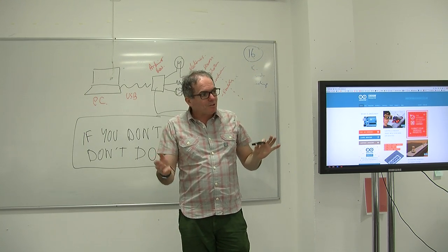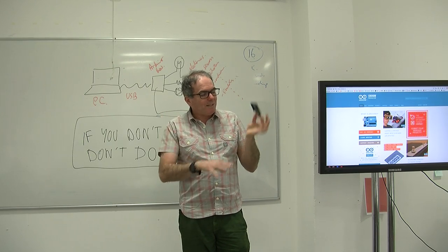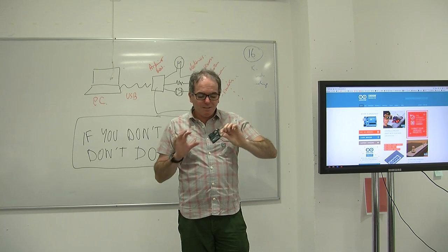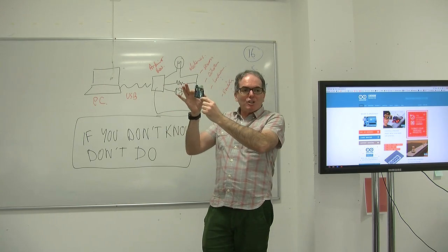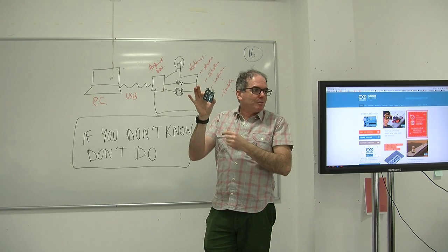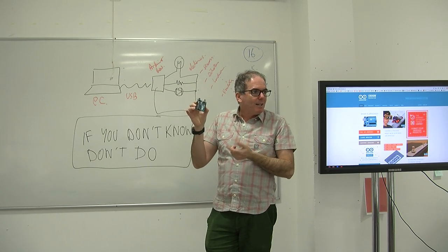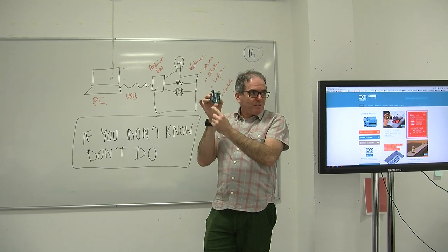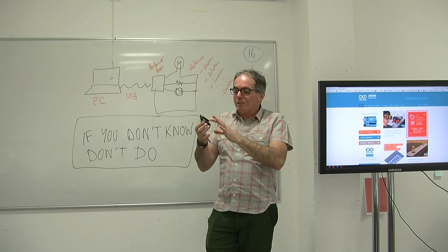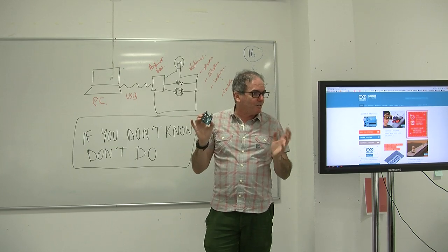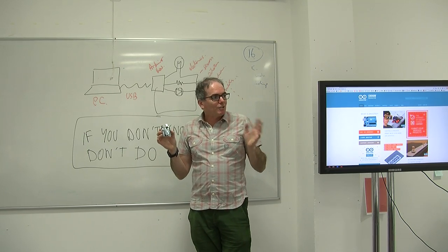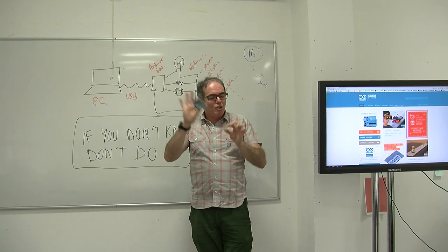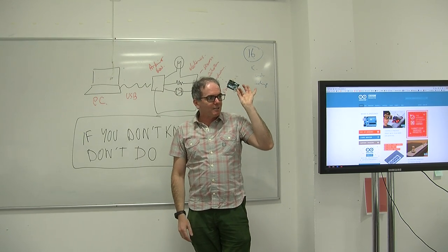If there is any component with some electronic circuitry, some integrated circuits like here, an integrated circuit is any of these black things with legs going on each side. These are called pins. And this is called a dual inline chip. So you recognize a chip, yeah? It's an integrated circuit. So anything like that, don't touch with your fingers because you're statically charged and you can damage it. So to be safe, you always hold things by the edge or where you see a grounding.